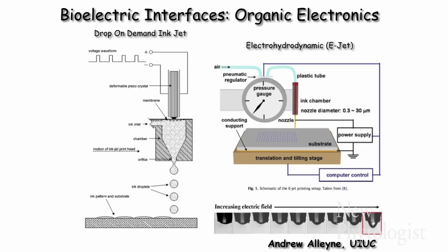Now, how do you put this mess together at this scale? So originally we were going to make a robot that was 1 millimeter long, and we realized we couldn't get the electronics that small. So we're looking at a centimeter. Now, the standard way of doing this is with organic electronics where you use inkjet printing. Inkjet printing produces features that are on the order of about 100 microns. It's really hard to get a feature smaller than about 100 microns, and that's just too big for this. We fooled around with it. All the inkjet printers that you use are made out of plastic. If you try to use any fancy solvents, you melt the inkjet printer, which we did twice.